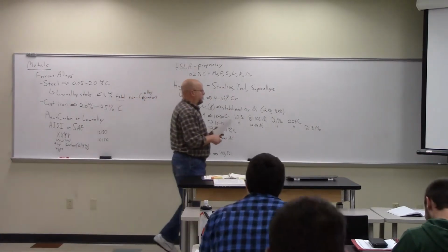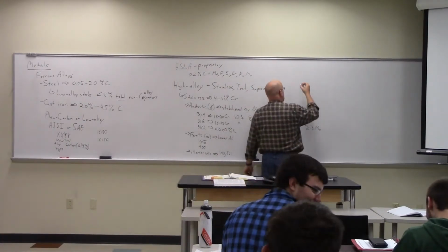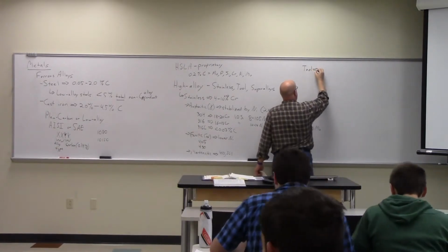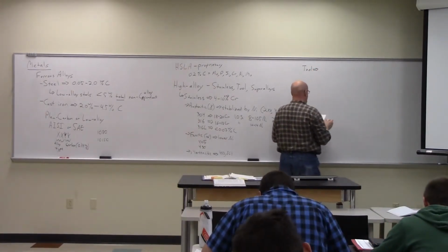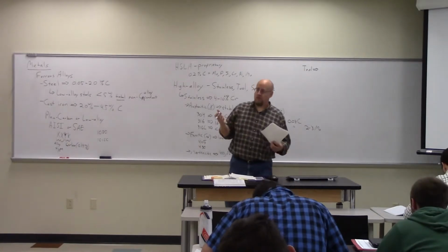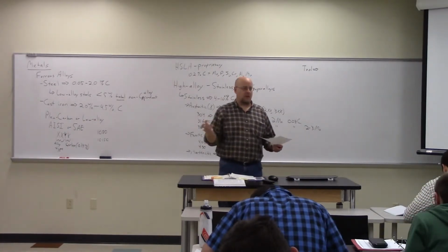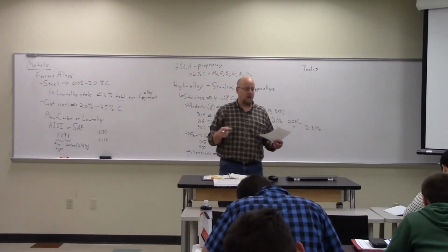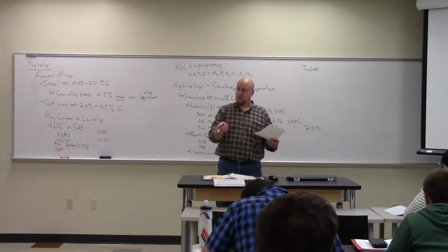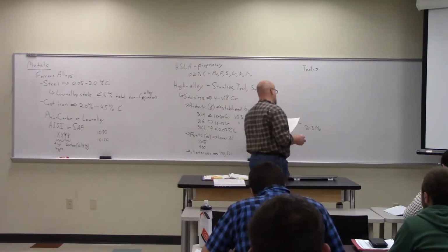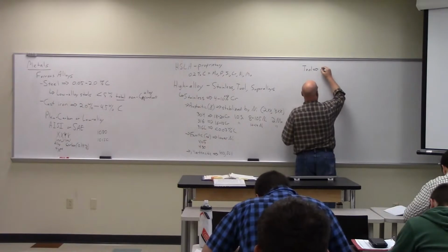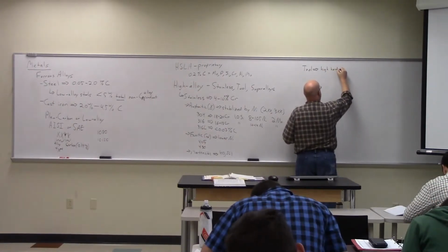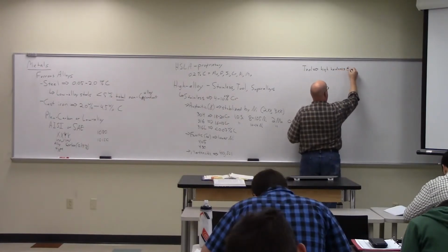All right, so those are the stainless steels, then the tool steels, also within the high alloy content, right? The purpose of a tool steel is to maintain high hardness at high temperature. When I'm cutting something on a lathe in the machine shop, I'm generating tremendous temperature increase because of friction. So the whole point of a tool steel is high hardness at high temperature.